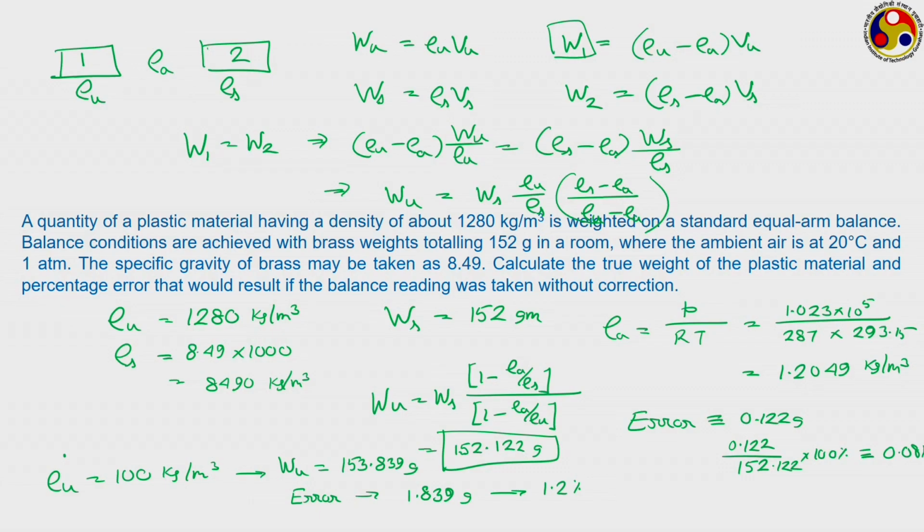So, this buoyancy effect is something that we have to be very careful of during the measurement. Of course, the use of temperature control chambers, avoidance of the convection currents, those are also important, but those we can't eliminate by using mathematical means, which we can do in case of buoyancy.